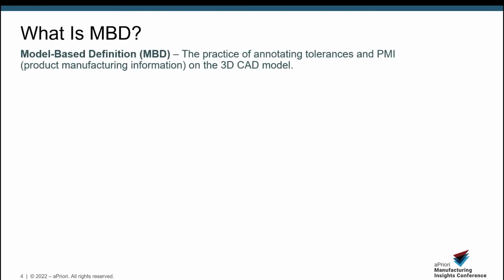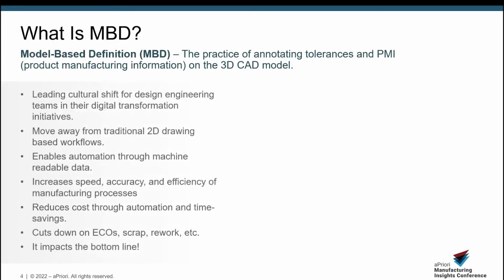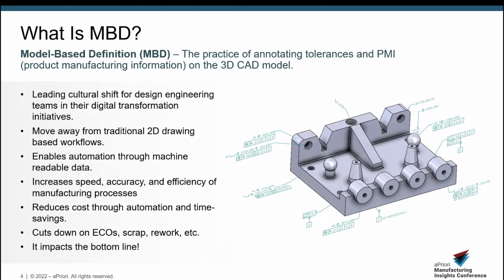So what is MBD? Some may say it stands for Manufacturing Builds Drawings, which in many cases is true based on traditional 2D workflows. But that is exactly what we are looking to move away from. MBD stands for Model-Based Definition, and is the practice of annotating tolerances and PMI data on the 3D CAD model. So MBD serves as this foundation of the digital workflows in design and manufacturing. And by now, most engineering teams are beginning to adopt and engage in MBD practices. And so the benefits of going to MBD will have a major impact on engineering and manufacturing workflows.